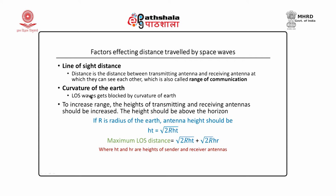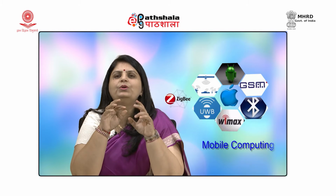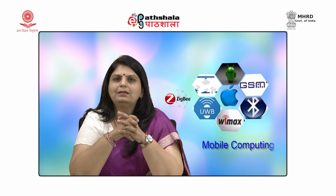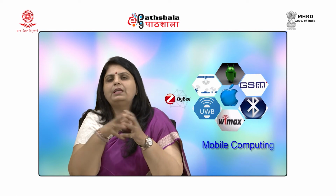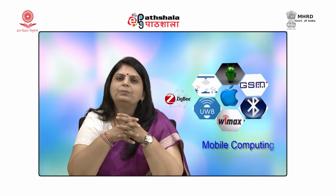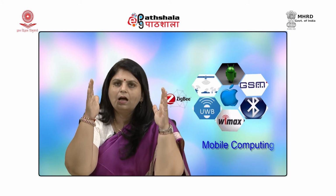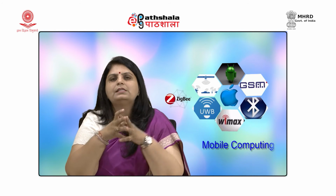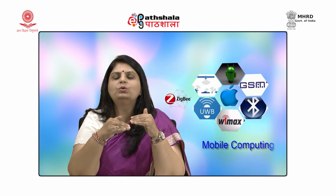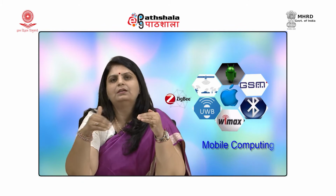So, what do you do to increase the range? If something is blocking your vision, what do you do? You just stand on your toes and try to peep. Here also the same thing is done: the horizon, or the spherical nature of the earth, is blocking the line of sight view. So, what should you do? You should place the antennas high above the horizon, as simple as that. If you see from above, you will be able to escape the obstacles which are below.